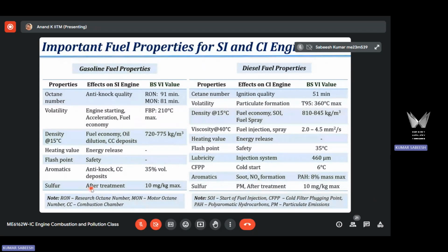We have discussed this in the gasoline case also. It affects the three-way catalytic converter. It makes catalysts like platinum inactive, and catalysts like platinum are very expensive. So you may have to change the catalyst often, which means higher maintenance cost. So here also the aftertreatment system is affected by sulfur. I will give more detail later on.